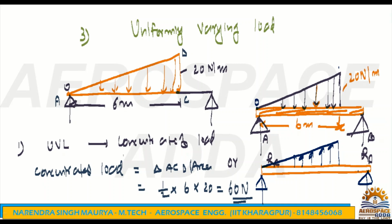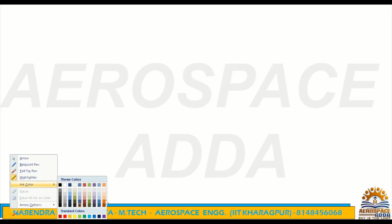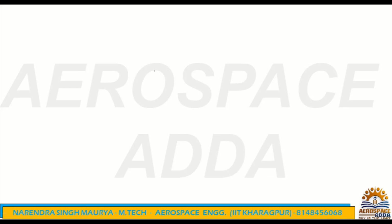You have converted the UVL into a concentrated load, and the concentrated load will be acting at one point that you know very well. So what is that point? We have to find the centroid of the triangle, because the centroid is the point where the converted concentrated load of the UVL will be acting. So now this is my triangle.